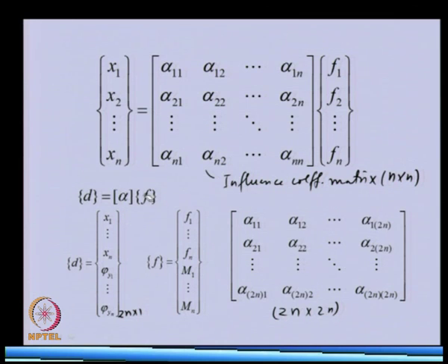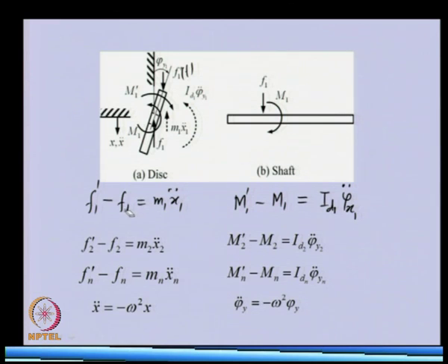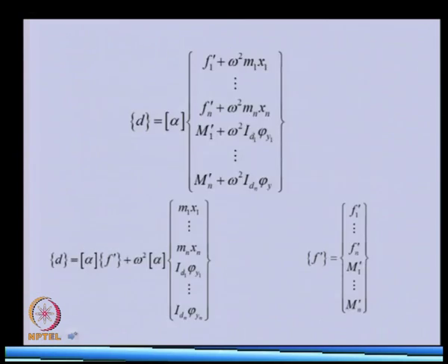F is the reaction force onto the shaft. So, from these equations we can solve for F1, F2, Fn, M1, M2, Mn, and we can substitute in that vector, and we have done this here. Even we have considered the harmonic motion, so omega square terms are also coming. You can see now, earlier it was static force, now because of dynamic force